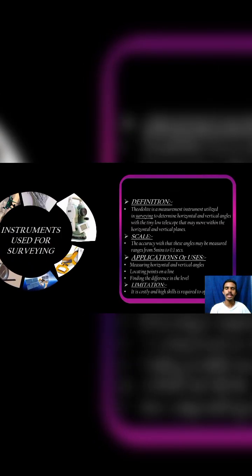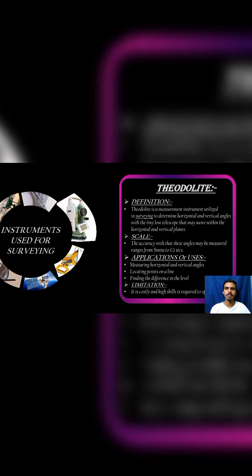The next instrument is theodolite. Theodolite is a device that is utilized in surveying to determine horizontal and vertical angles with a tiny telescope which moves within the horizontal and vertical planes. The accuracy with which these angles may be measured ranges from 5 minutes to 0.1 seconds. Applications or uses: measuring horizontal and vertical angles, locating points on a line, finding the difference in the level. Limitations: it is costly and high skill is required to operate this device.